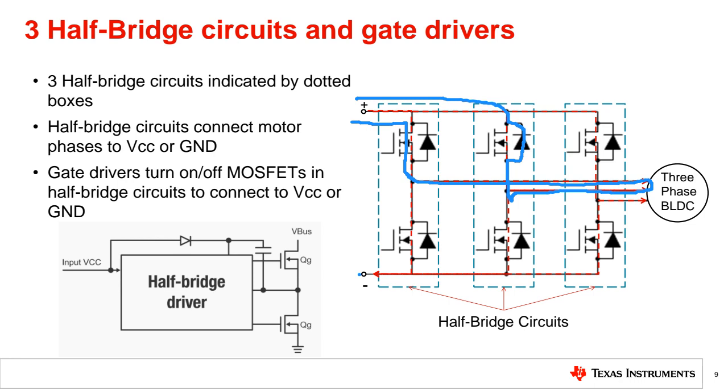Every 60 degrees, one semiconductor, one diode will be active. In one cycle, you will supply energy to the inductance of your motor, and in another cycle, you will consume it. In the first 60 degrees you energize, in the second 60 degrees you will consume it. Because you know the brushless DC motor has winding. Winding means inductance.